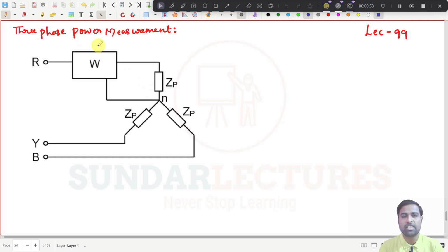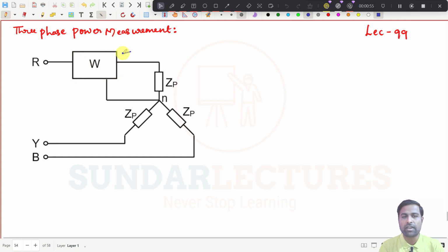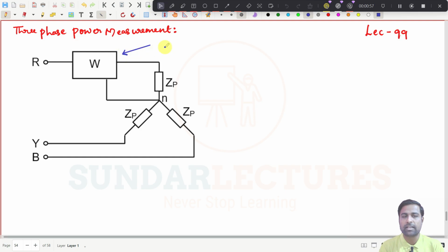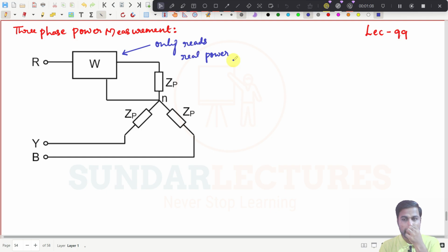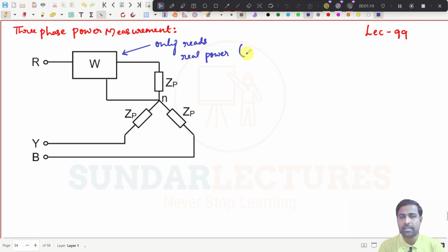So for example, see here, in a wattmeter, always you have to understand certain things. A wattmeter only reads the real power, right? What is real power? Whether it is single phase or three phase, both are the same. If it is real power, then it will be V phase times I phase times cos phi.